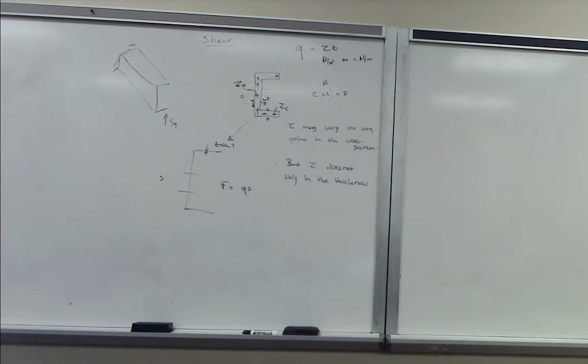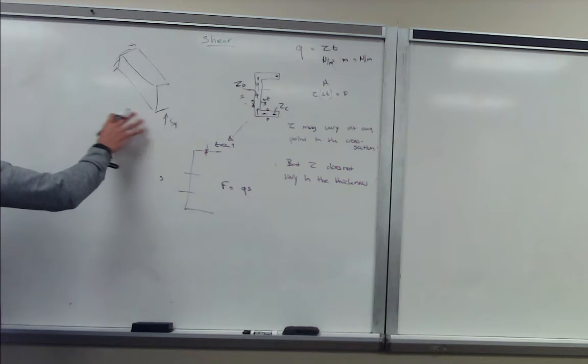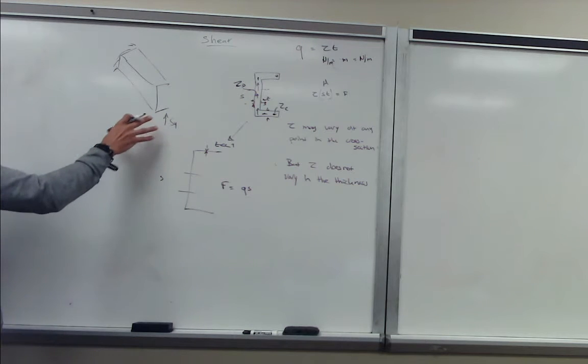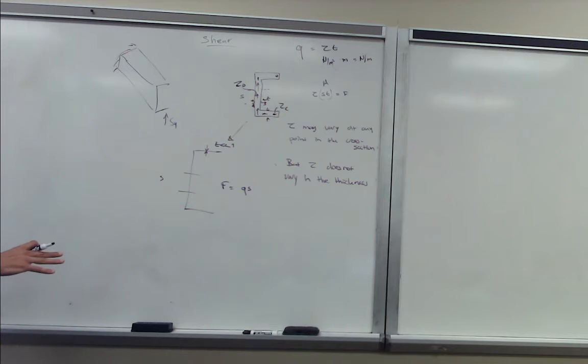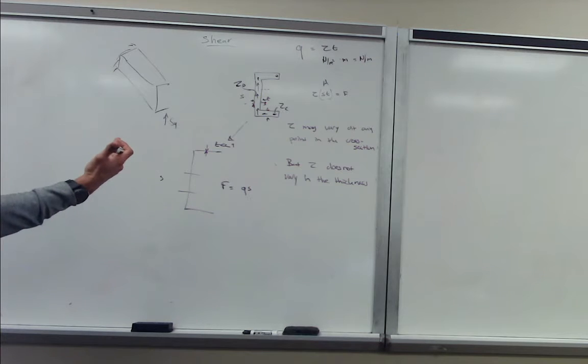That's also the unit of it. This becomes a bit simpler when we later identify, given a shear force, the shear flows it introduces instead of looking directly at the stresses. If we want to calculate shear stresses, we just multiply by the thickness at that location, and then we get our shear stress.